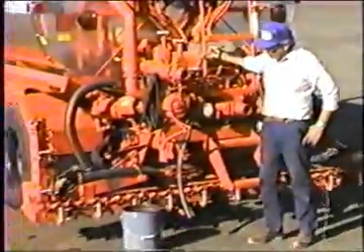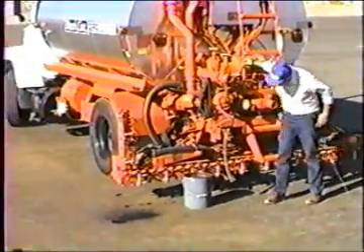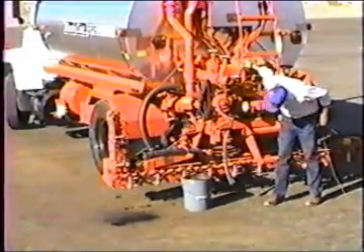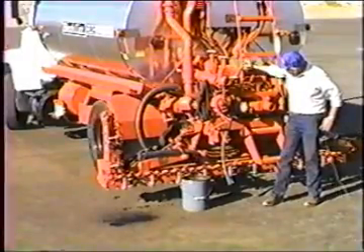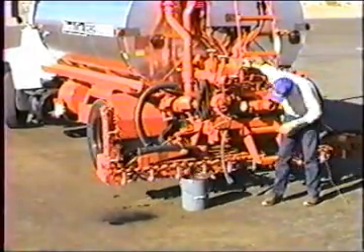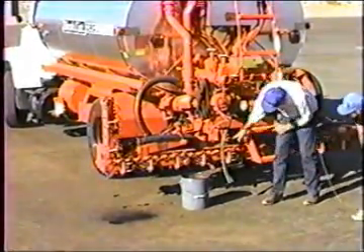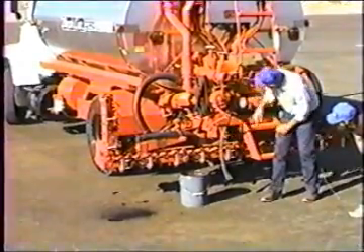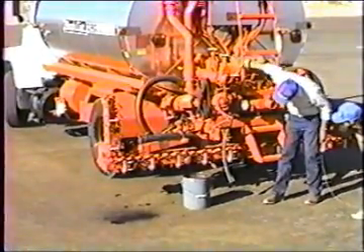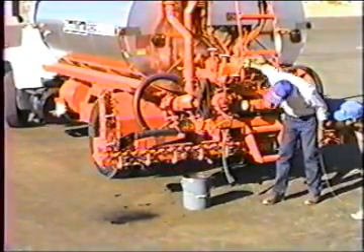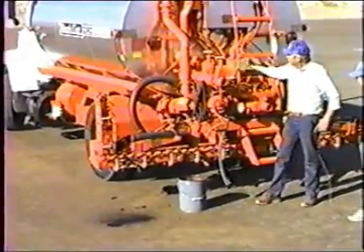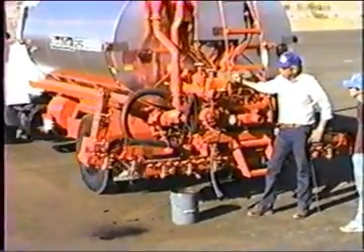For those wings to fold up and clear everything, the bar has got to be centered. You center it when you're at the back here, just by getting, see the slot down here and the blade, get that lined up to where they'll go together, and that's centered. No problem. Now you can lift that wing and there's no wreck.